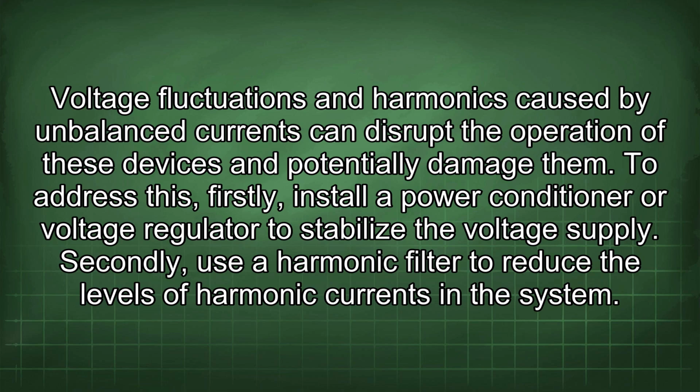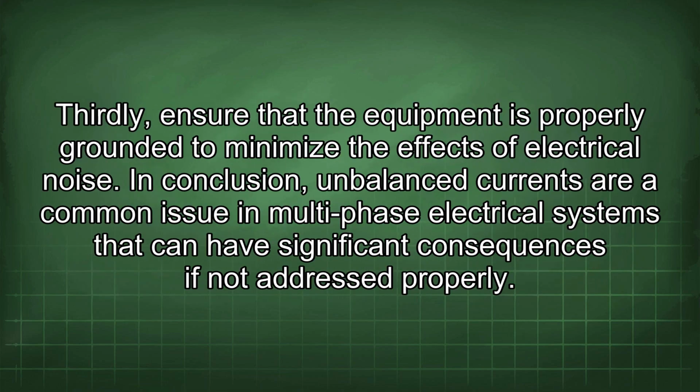Secondly, use a harmonic filter to reduce the levels of harmonic currents in the system. Thirdly, ensure that the equipment is properly grounded to minimize the effects of electrical noise.